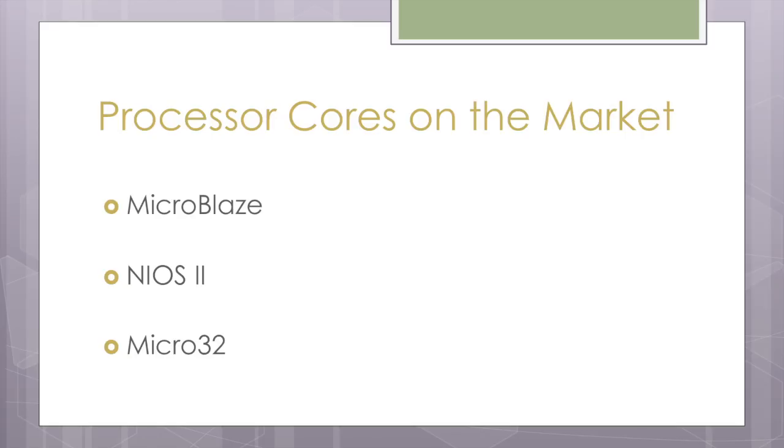It has 2 local memory buses that are used to connect the instruction and data memories. There is an on-chip peripheral bus to alleviate the system's performance bottlenecks. This is also designed to support the low performance and speed peripherals such as UART, GPIO, USB, and others.